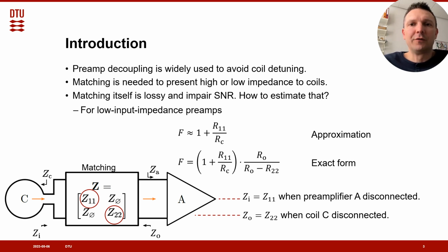There is a wide variety of networks to choose from, and there is no clear guidance for which circuit topology to choose for a particular implementation for better noise performance. The resistive loss of the network can significantly degrade SNR at the input terminals of the preamplifier. The process of identifying which component of the network is driving SNR degradation and how to minimize this effect has so far largely been based on the experience of the coil designer.